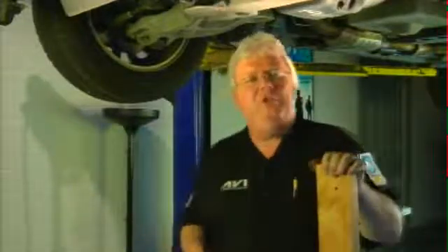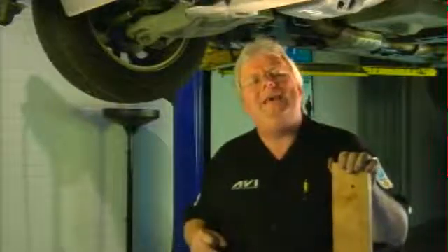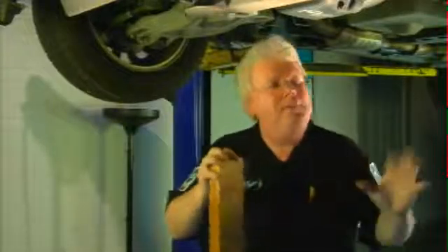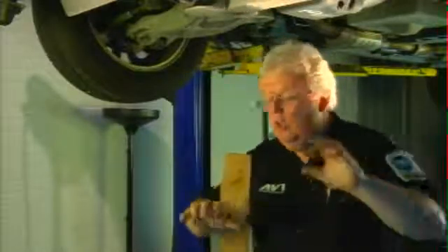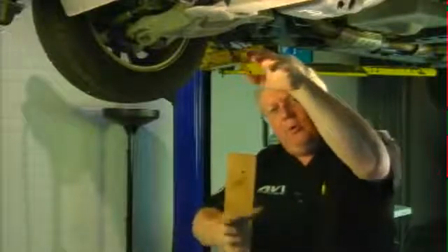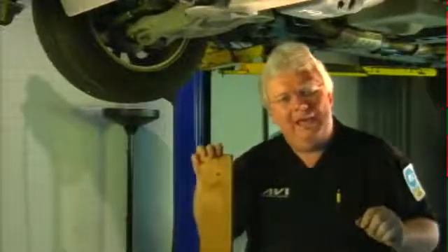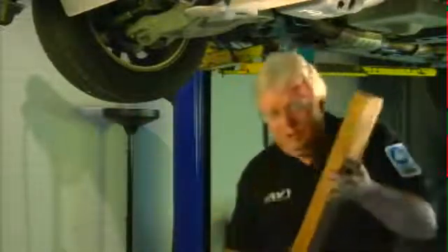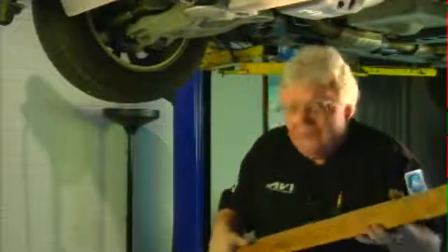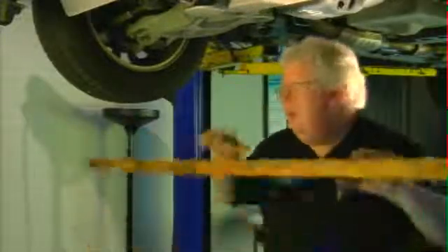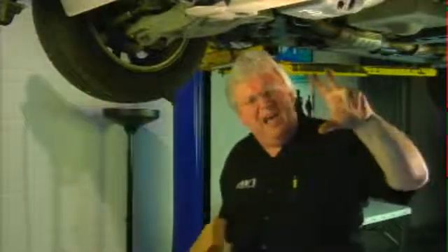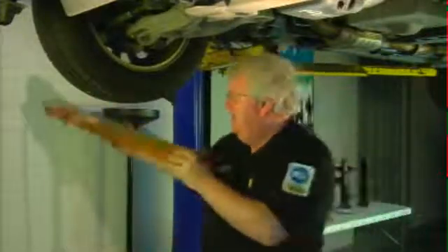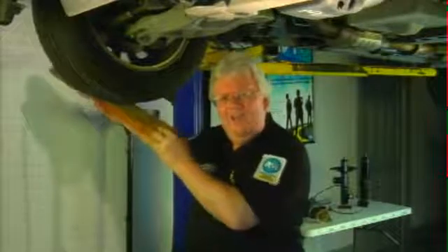Well, in the manual that you've got, your student study guide, it talks about the axial play on the ball joints. Now, radial play, we've discussed, is moving back and forth like that. Well, axial play is where you put a long pry bar or even a 2x4 between the ground. So we're coming from the outside like this. The vehicle's maybe 4 or 5 inches off the ground, and then we're loading that tire, pulling up on it